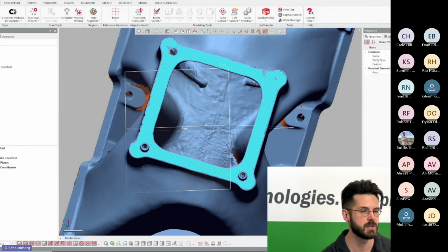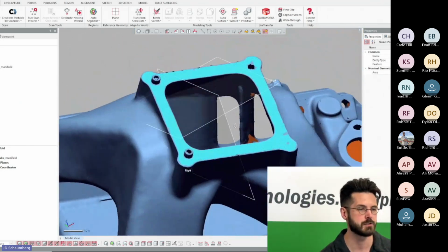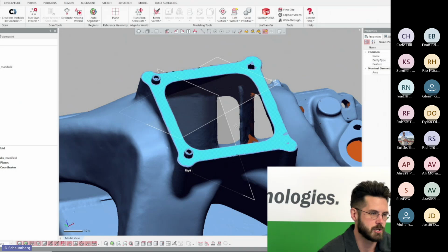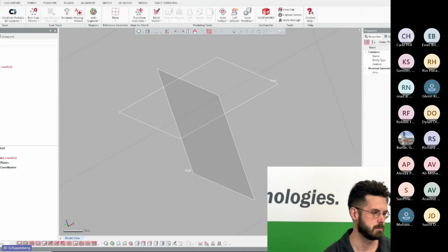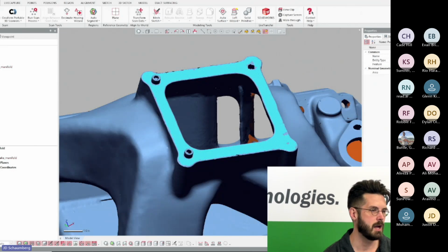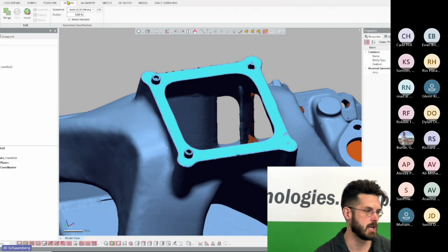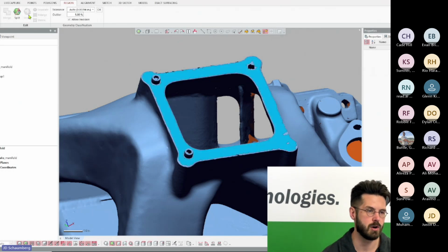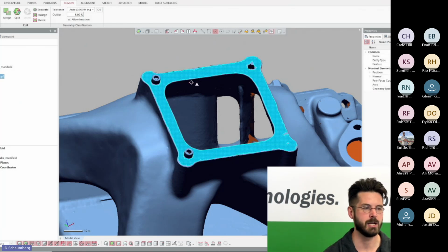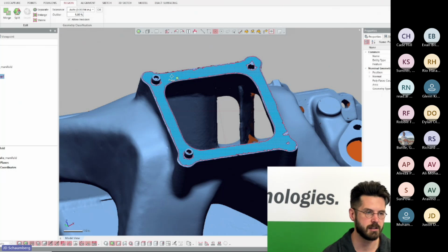Here you'll notice I'm actually not extracting things from the CAD model because we have no CAD model to extract from. Instead, what I'm doing is selecting scan faces, and I am doing what's called region grouping. Region grouping is something that's very unique to Design X. What region grouping does is when I insert a region on a selected area of the scan, it identifies that as a selectable patch. So now you can see I can select this region here.